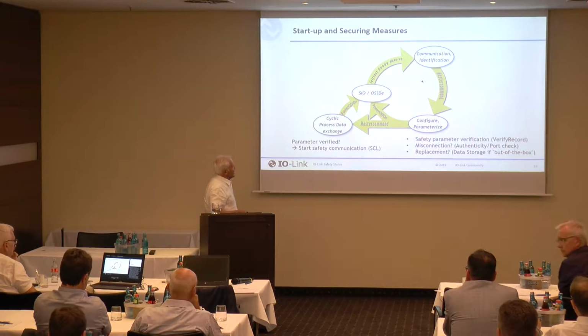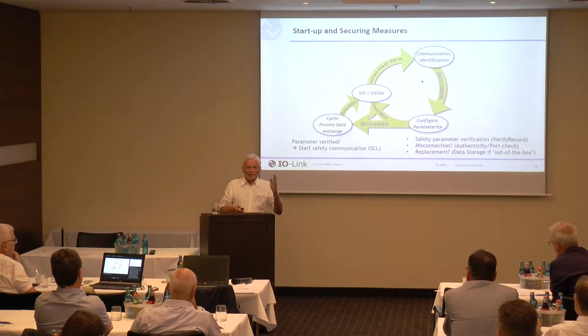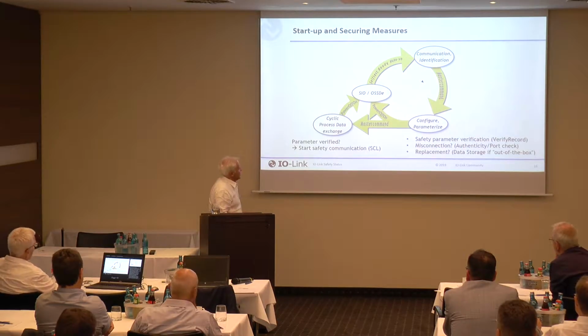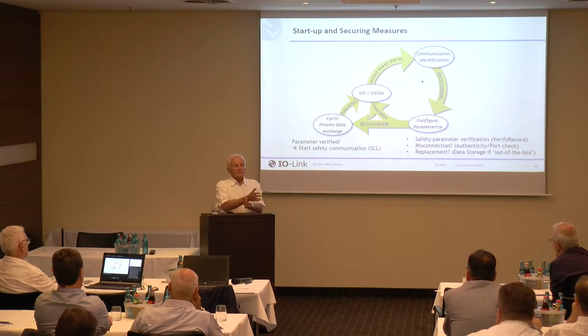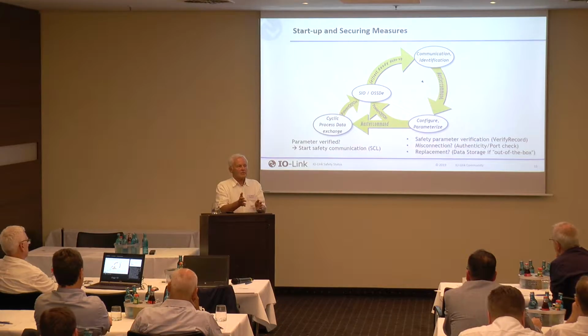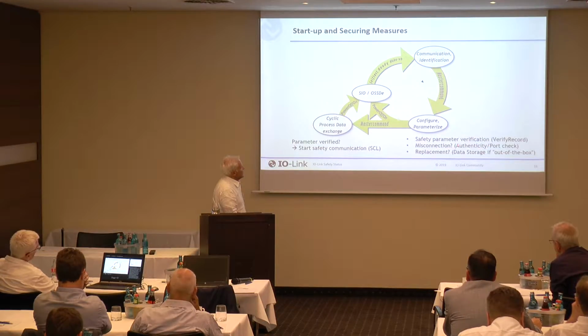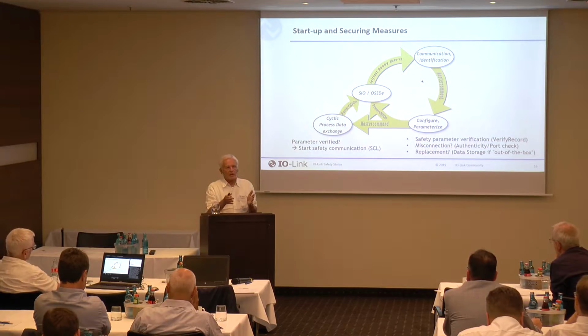Here we have a mechanism that is verifying the safety parameters in a diverse way. So the safety parameters are checked, and we have some authenticity checking. So we find out whether two safety devices are switched by chance between 2 ports. So the system is not starting. You get an event that there is a misconnection, either between 2 masters or between ports. It doesn't matter.